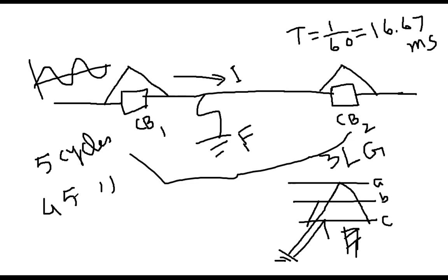And then again, there is a standard practice. You have to wait 45 cycles. Circuit breakers are designed accordingly. It is automated, not manual. At the minimum, you have to wait 30 cycles. This means 30 multiplied by that millisecond. That is the waiting time. And then what happens? Circuit breaker will reclose. Why will the circuit breaker reclose? To maintain the continuity, because we are assuming that the fault has disappeared. Fault has been cleared. It was a temporary fault. And then the system runs fine, stability maintained.